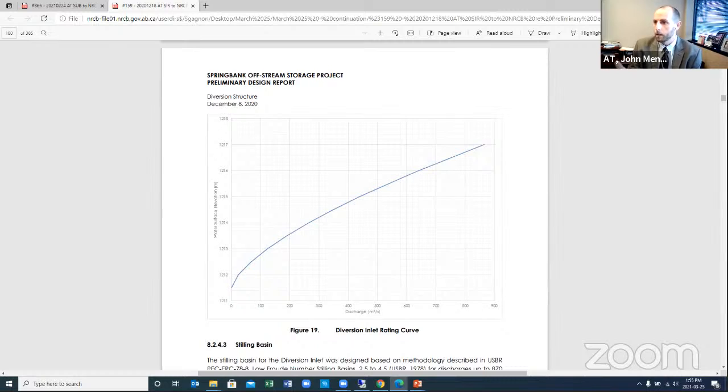The shape of that weir and its length dictates how much flow would go over it for a given elevation. An orifice, on the other hand, is a hole that water has to flow through. So instead of just having that surface friction on the bottom, it has it all around all the sides, and it restricts the flow and causes flow to slow down further.